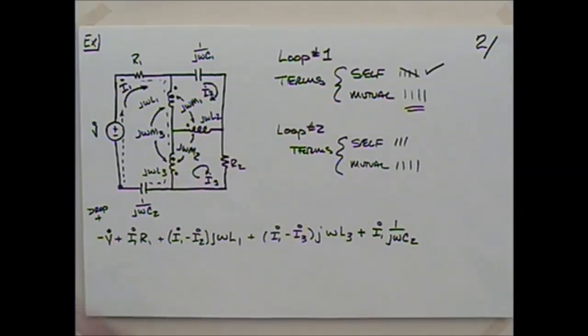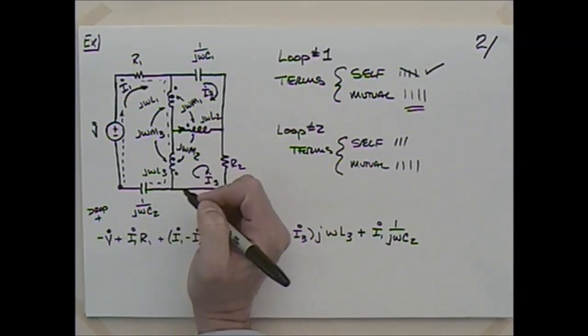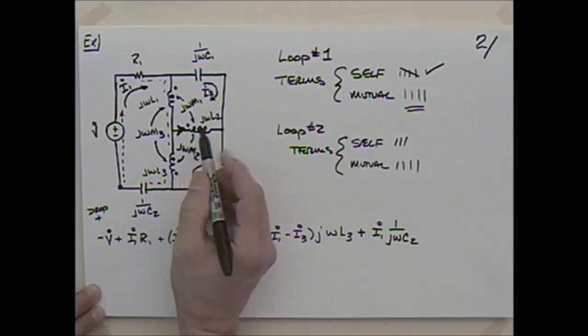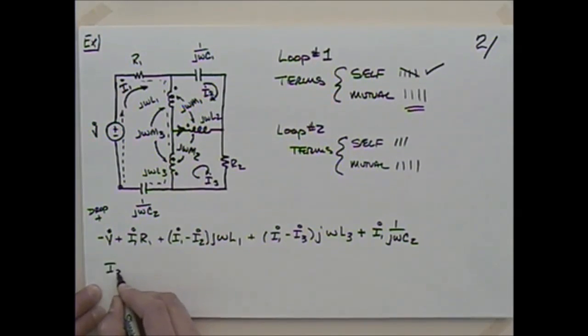We might start out with the current. A lot of times what I'll do, I can choose that it's I2 minus I3 or I3 minus I2. Why not make my life kind of easy and say, well, I want to find this current right here because that's going into the dot, right? So what current is that going to be? Going into the dot, that should be I3 minus I2, shouldn't it? I3 minus I2.